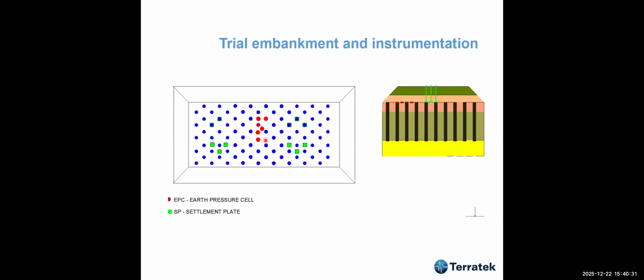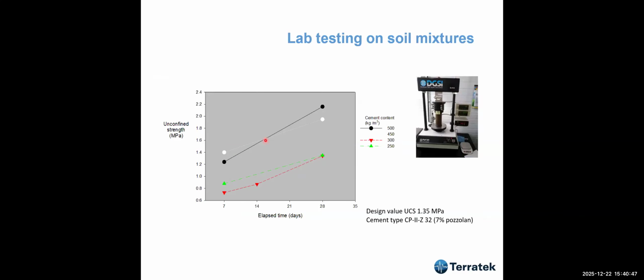And also we did a trial embankment, and this trial embankment was fully instrumented. I had the opportunity to analyze the results. We used settlement plates, we used pressure cells, we used piezometers, etc. And we published these results in a conference in San Francisco, I think 2015. And we did a lot of laboratory testing on soil mixture, varying the time to take the sample to failure, and varying the cement content.